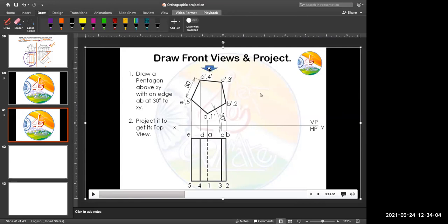So from here you have to carefully observe that from the top, the line coming from D will be visible. The line coming from C will be visible. The line from E, again it is open on the upside, so it will be visible. The line from B, it is open from the upside, so it will be visible.